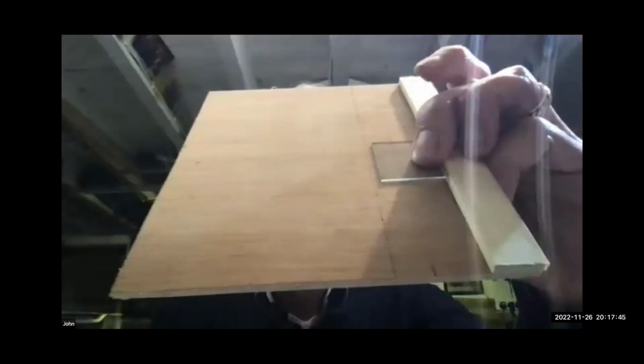Measure whatever you want to cut, put a line on it. Make sure your glass is clean. Place it on the board. Take, in this case, a piece of wood. Put that on, use that as a rule. And this is where it all goes wrong. It's not brilliant, but you can cut quite small pieces of glass for making windows.